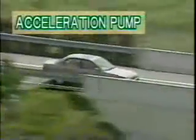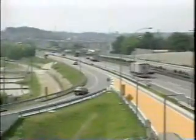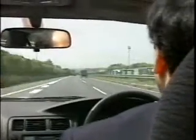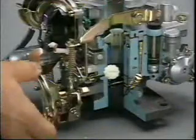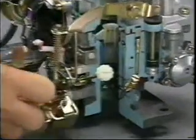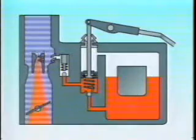Now let's take a look at the acceleration pump. We all know that to achieve quick acceleration, the driver needs to depress the accelerator pedal suddenly. The acceleration circuit is designed to prevent engine hesitation during such sudden acceleration. With the pump-type power circuit, when the throttle valve is suddenly opened, the pump lever depresses the pump plunger. This increases the flow of fuel from the acceleration pump jet.